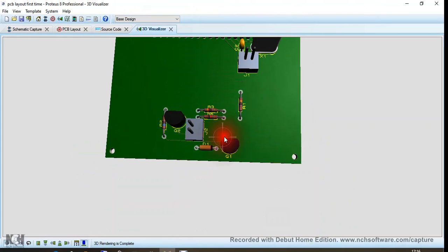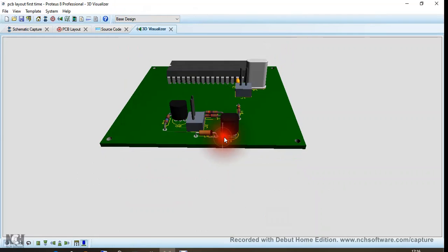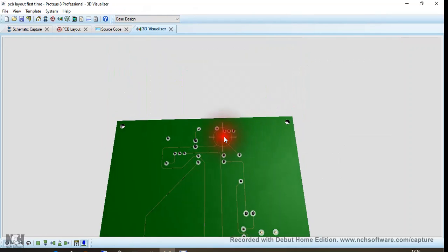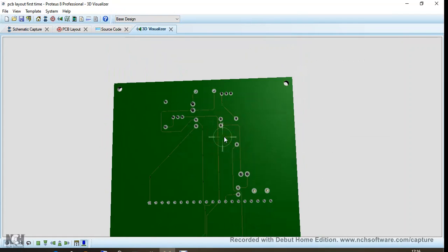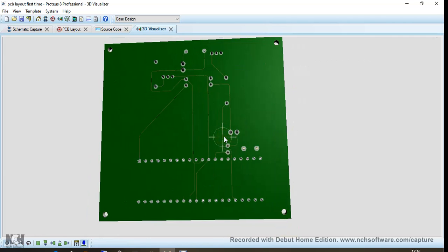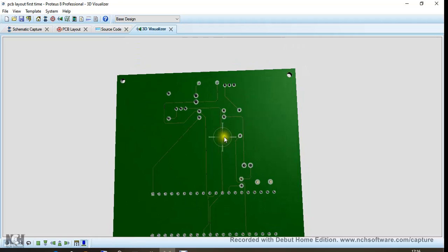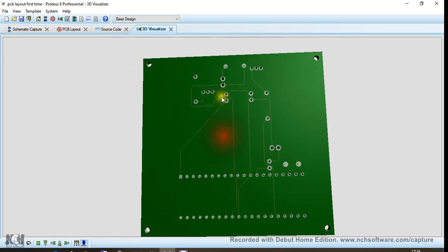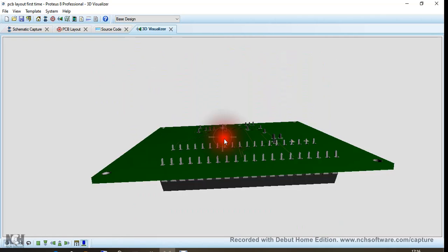See all those tracks, from the transistor to the resistor, from the transistor to J2, which is a light bulb, and you see we have some underneath, because this is where you're going to do the soldering part, so they must be right underneath. So you're going to be doing the soldering on this side. This is where you see them tracks. So you see this track from this pin of the microcontroller. All these tracks are right below or underneath the board.